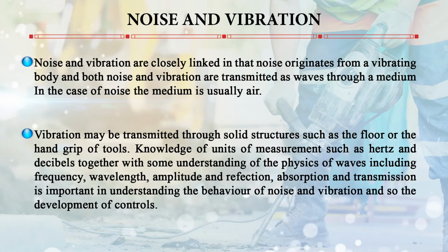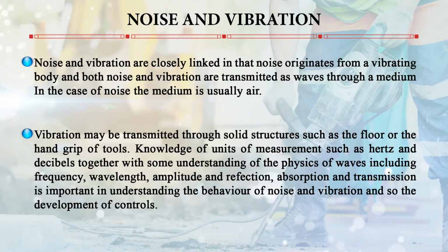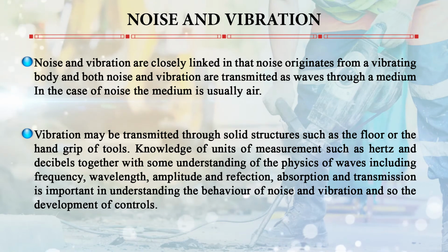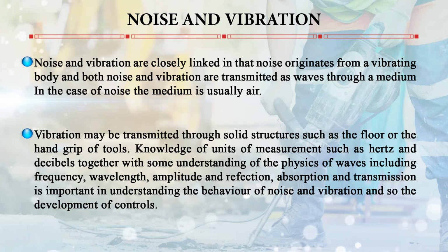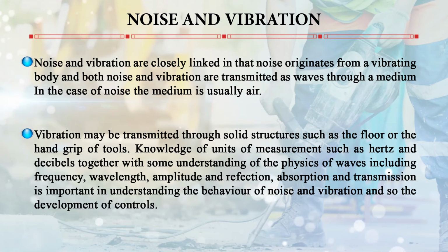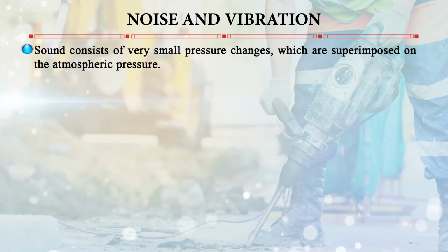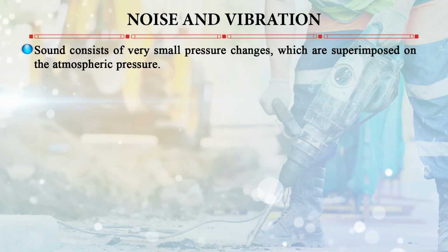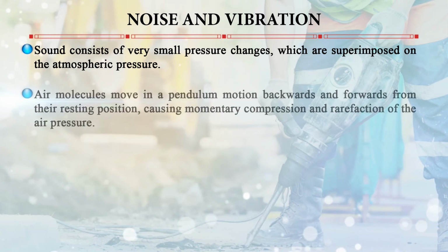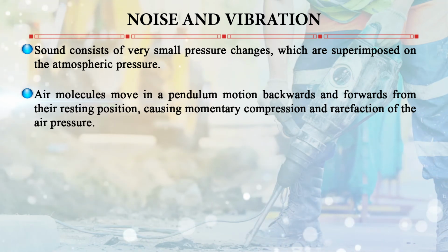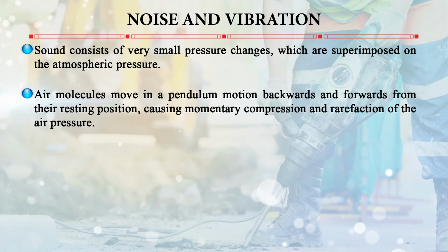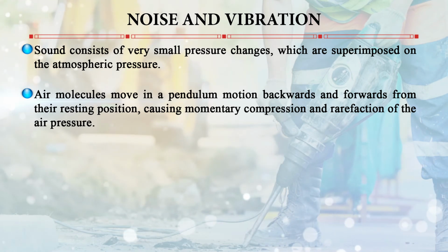So knowledge of units of measurement like hertz and decibels, together with some understanding of the physics of waves like frequency, wavelength, amplitude and reflection, absorption and transmission, is most important in understanding the behavior of noise and vibration, and so the development of controls. Sound consists of very small pressure changes superimposed on the atmospheric pressure. Whenever air molecules move in a pendulum motion backwards and forwards from their resting position, that causes momentary compression and rarefaction of the air pressure.